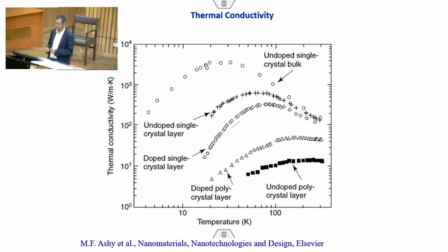of the phonon spectrum. So, high frequency phonons can be blocked by the alloy scattering because wavelengths are of the order of a few atomic spacings. Okay. So, phonons can have different wavelengths, and therefore their scattering will depend upon the relative grain size of the materials. So, now comes the nanoporous material.